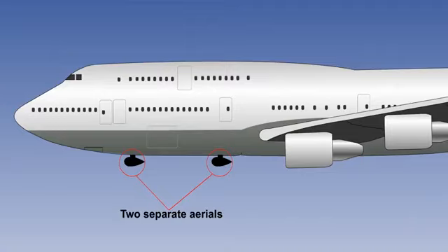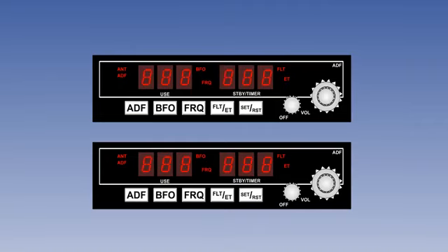Multipath fading can be overcome by positioning 2 or more receiving antennae in different places, so that at least one will receive a good signal. This is called space diversity. It can also be overcome by using 2 transmitters and 2 receivers, each pair tuned to different frequencies. This is called frequency diversity, and one of the receivers will usually receive a good signal.